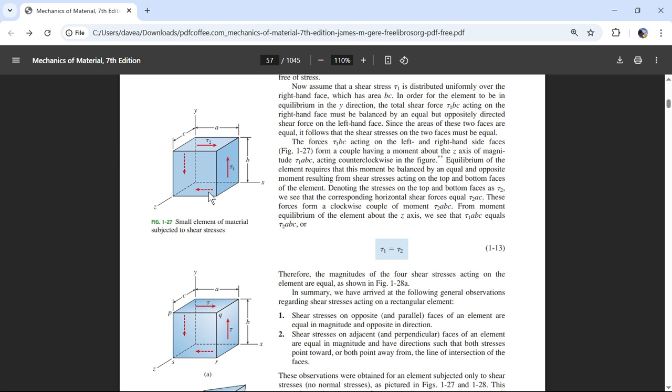But the cut surface on that 45 is going to be the area of that rectangle, with a depth of 1 millimeter and then a height of whatever this diagonal is. And so if this surface is 1, this is 1, this diagonal is from the Pythagorean theorem: this side squared plus this side squared, square root of that is this length.